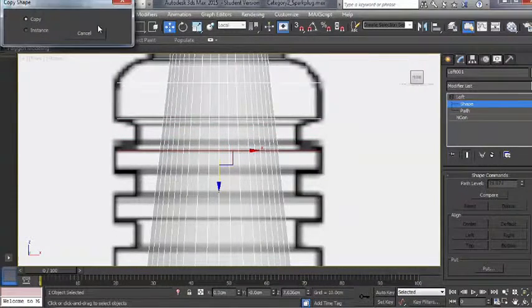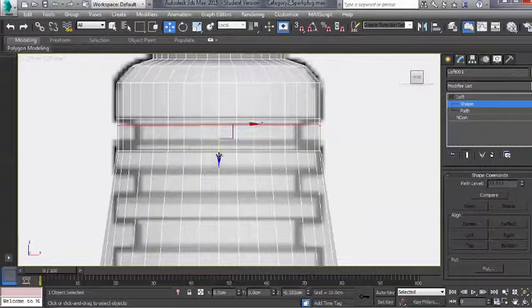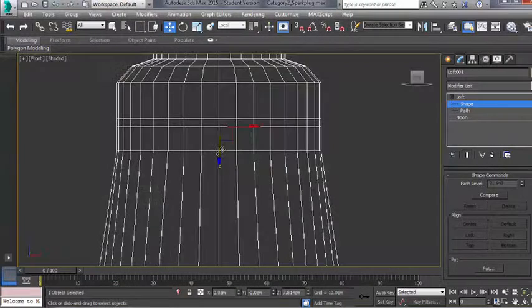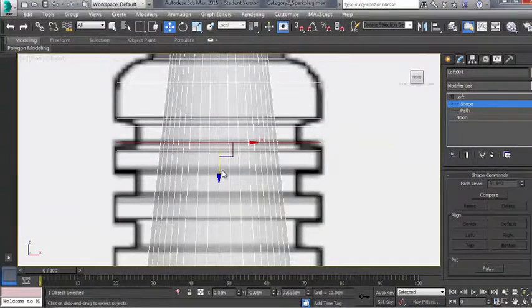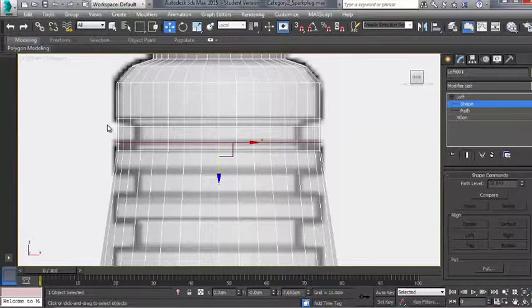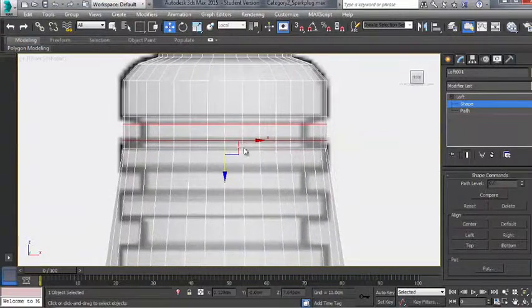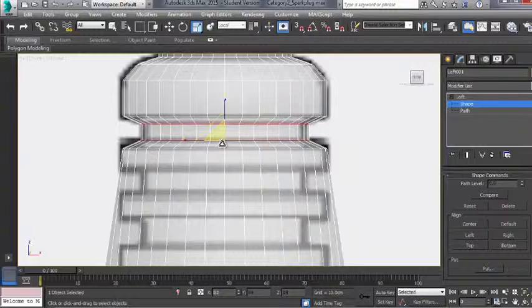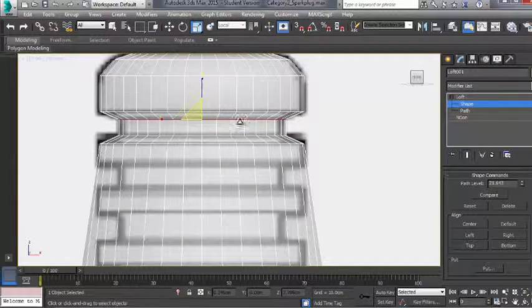So if I skip over to the other side there, and I put the extra loops in the middle. So I've put the 2 loops in there, and I can select both of those at the same time, hit R to go to scale, and then scale them both in. So it saves you a bit of work if you do have to do multiple scaling.